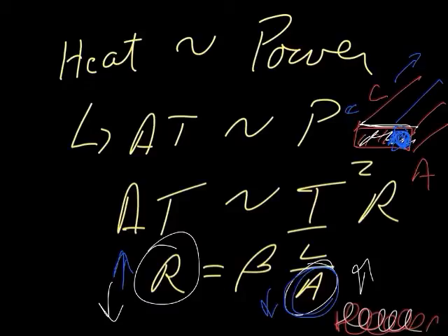So as a MEMS designer, I can't usually change the thickness because we're designing to PolyMUMPs, and PolyMUMPs at Poly 1 is a certain thickness, and at Poly 2 is a certain thickness. We can't change the thickness. What can we change? The width. Okay? All right.